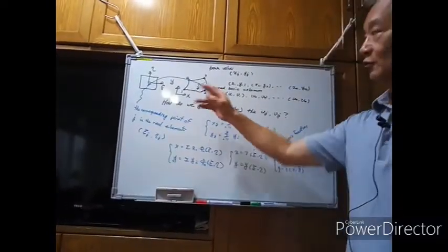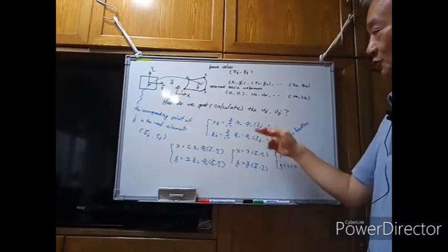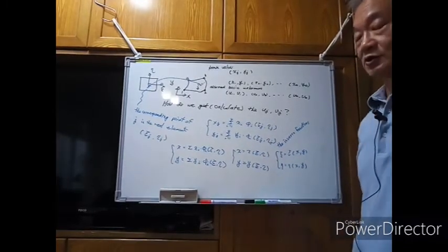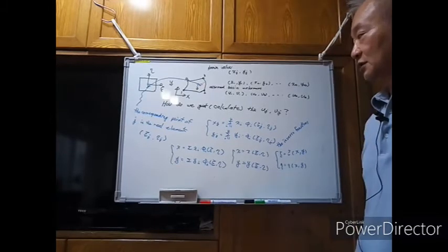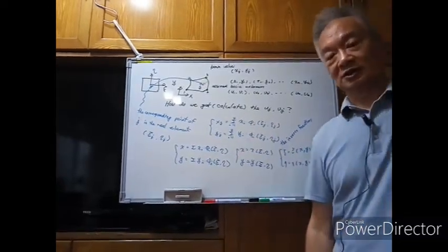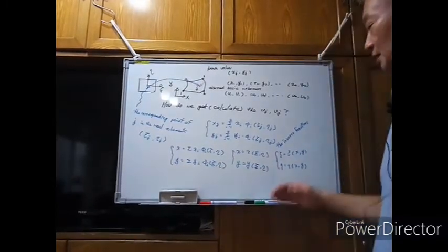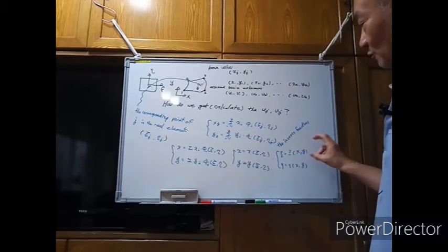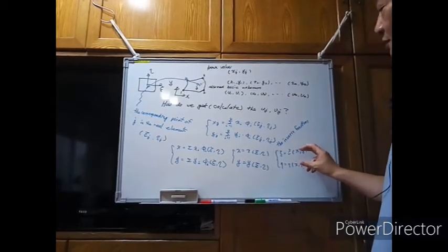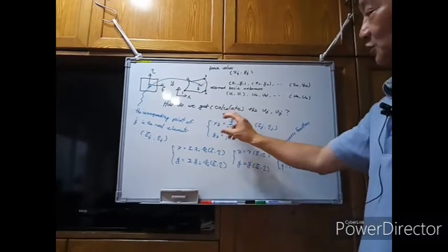If we use only the 4-node element, the shape functions are only first degree polynomial functions, and totally we got only 4 functions and the 4 xi or 4 yi. So it will be easier to solve the inverse functions. If you solve the inverse functions, then you can replace the x and y by the xj and yj.